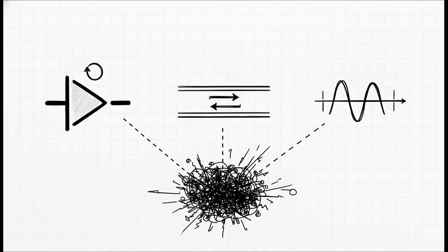Well, first you've got the diode's own hesitation time, that reverse recovery we talked about. Second, there's the travel time for that electrical echo to go down the wire and back again. And third, you have the rhythm of the power source itself, the time between each electrical pulse you're sending in. When those 3 timings get into the same ballpark, the whole system just goes haywire.